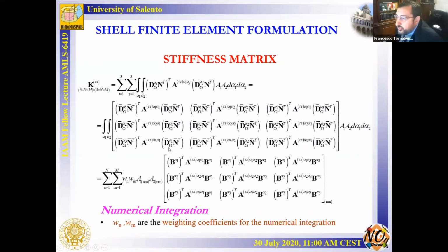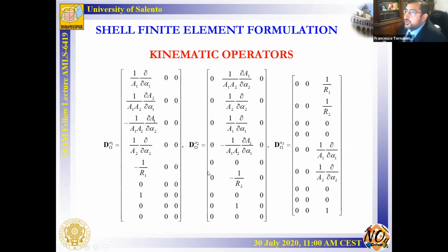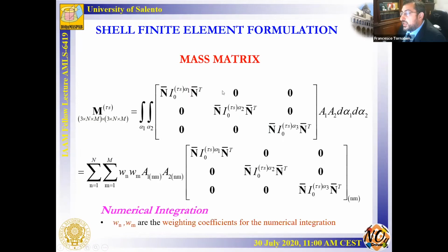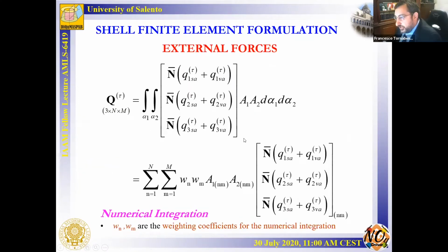It is important to notice that to evaluate the stiffness matrix in all the points of the reference surface, obviously in discretized form, I need a numerical technique, in particular a numerical integration technique, as I exposed before in this lecture. Also, I have used the kinematic operator as reported in this picture, and then I can also define the mass matrix and external forces.